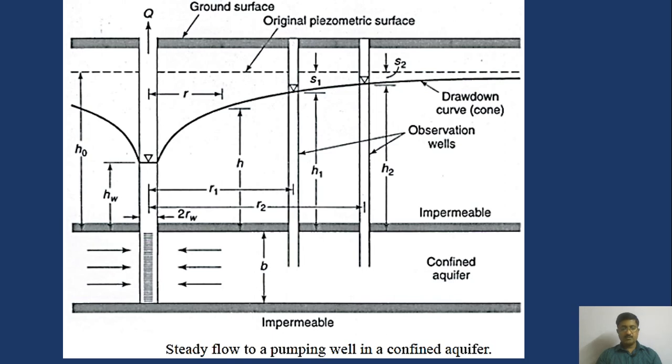As soon as the pumping is stopped, the depleted storage in the cone of depression is made good by groundwater inflow until the static level is reached. This stage is called recuperation or recovery, and is an unsteady phenomenon. So recuperation time depends upon the aquifer characteristics.